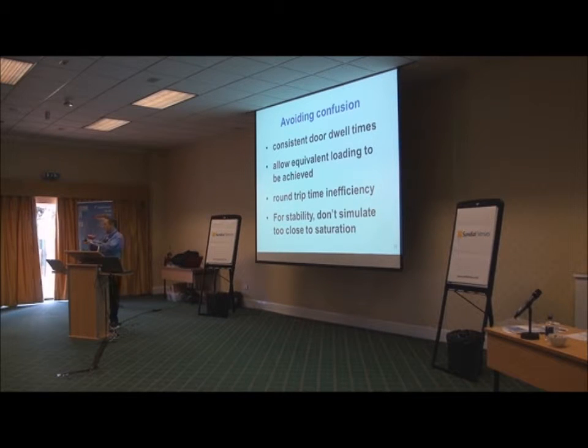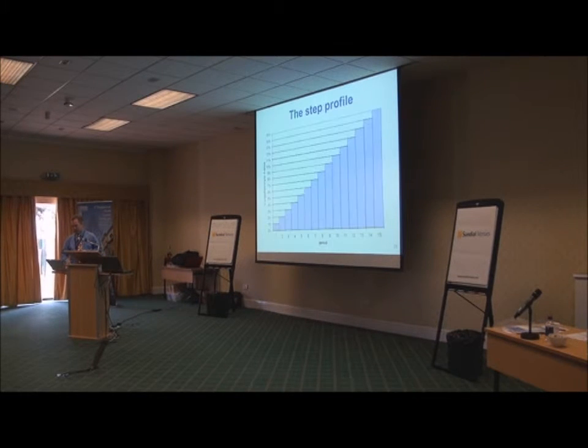And because people go from round-trip time calculations and design at the saturation point, basically our maximum handling capacity, we're expecting that we can just about get that 15%. Yeah? If you then give it 15.1, you're stuffed, or if you extend your door dwell times by a second, you're stuffed, the whole thing collapses. So basically you end up with people simulating round-trip time calculations, but they've just gone over the edge and the whole thing collapses. And then they give me a call. And I spend all my time helping people understand the differences, and I'd really rather spend more time on the beach, really. So I want to make it simple for people.